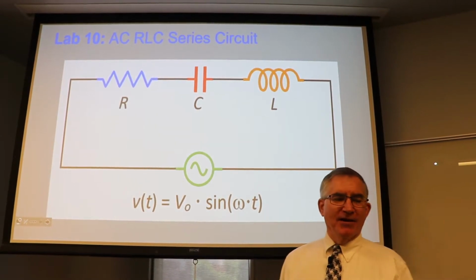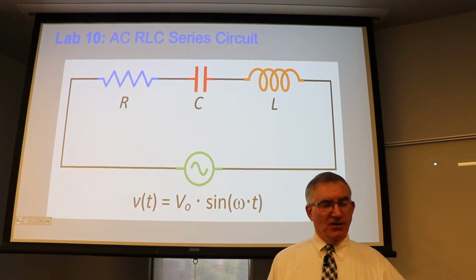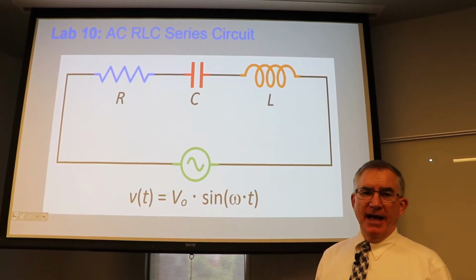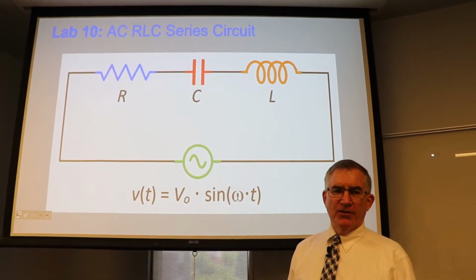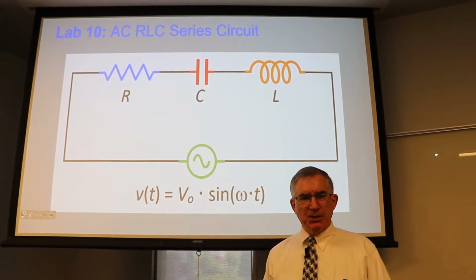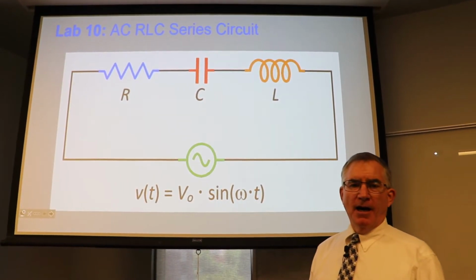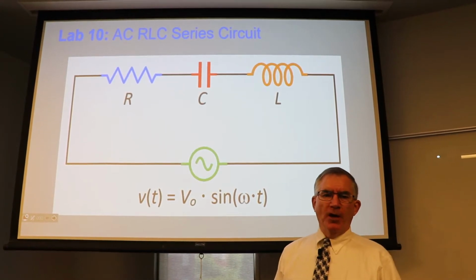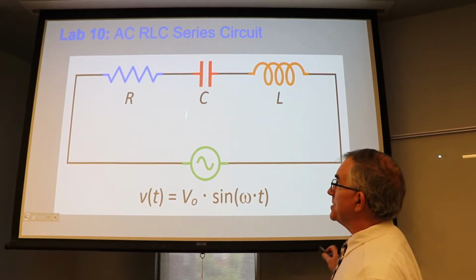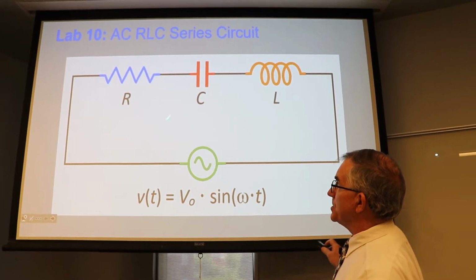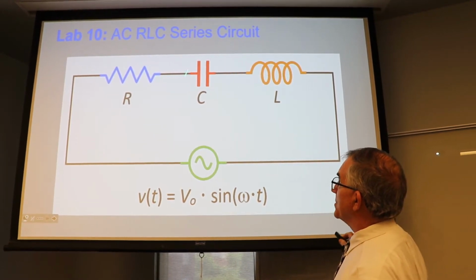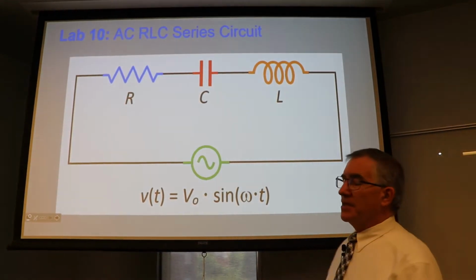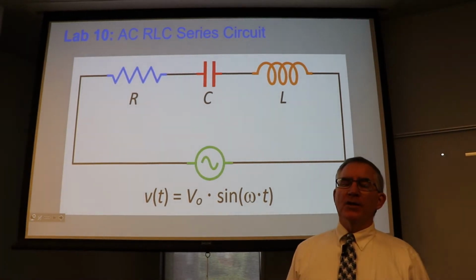And it's amazing. Our little 850 Universal Interface has a signal generator in there that allows you to continuously change the frequency up to about 60,000 hertz. So we're going to run that through these three devices that we've studied: the resistor right here, then the capacitor, and the inductor. And it doesn't matter what order they're in in the circuit.